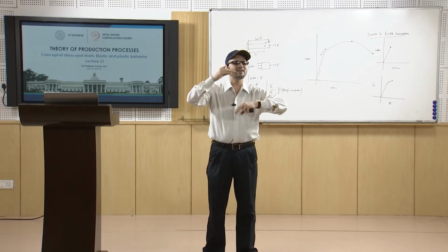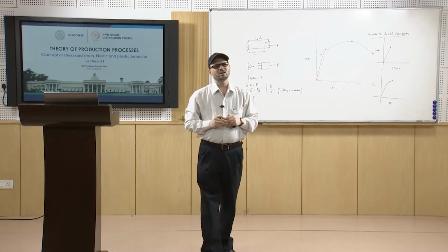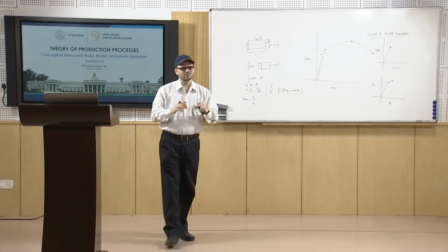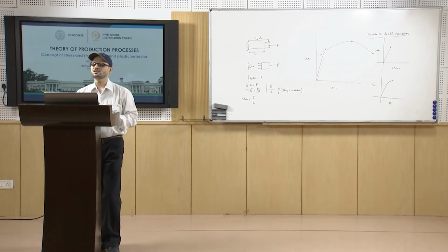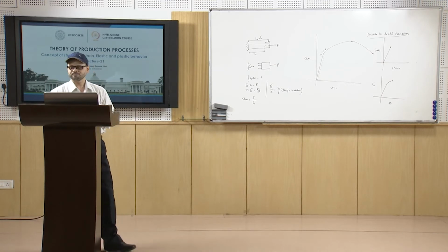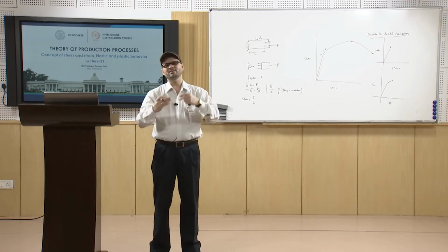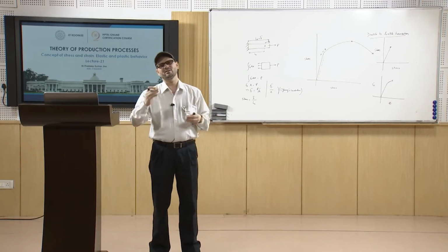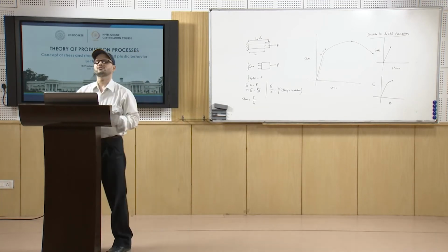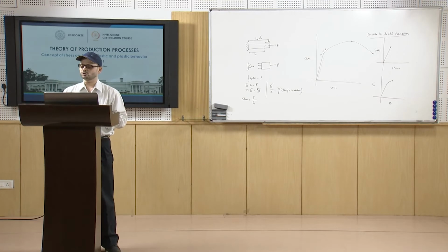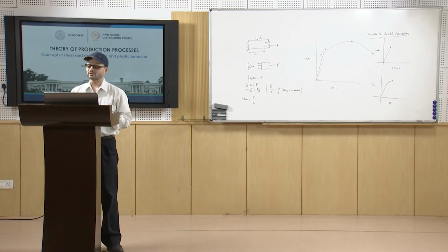If the material is subjected to these fluctuating stresses for a long period of cycles, the failure occurs at smaller values of stress, at which in the normal case it will not fail. That is known as fatigue type of failure, and you have to design the material against this fatigue, and you have some empirical relationships which work for such type of failure. Then you also have the delayed fracture, which occurs in the case of stress rupture failure.